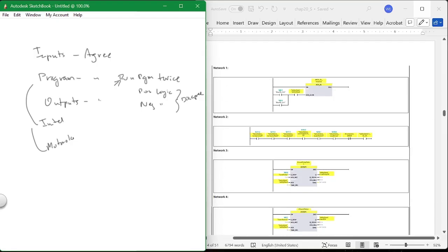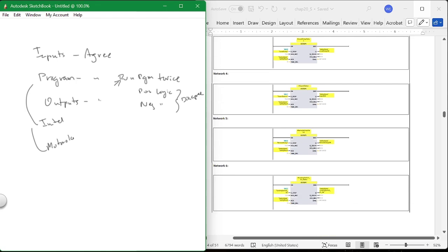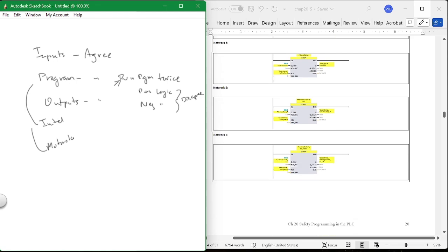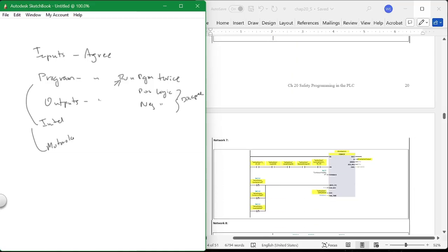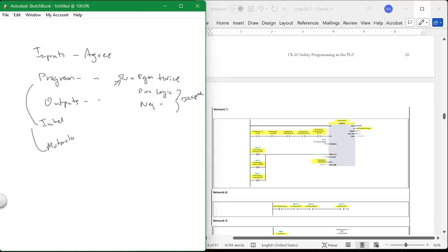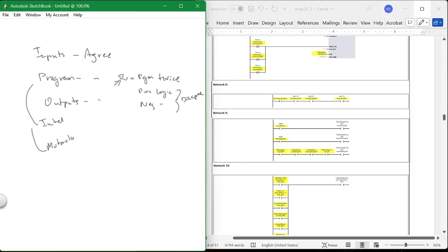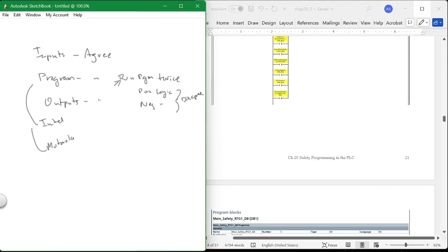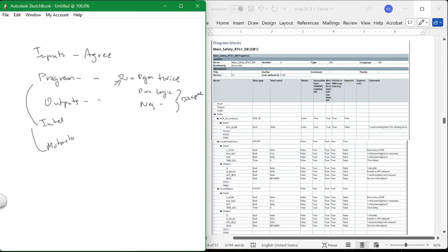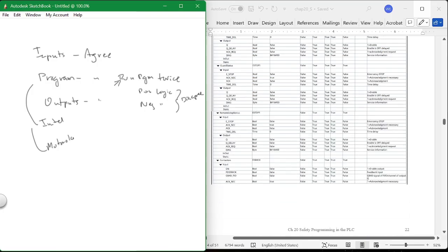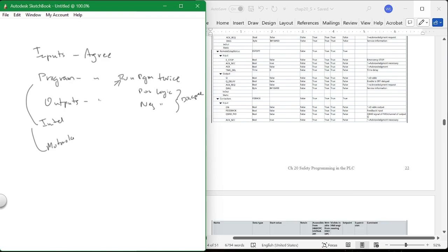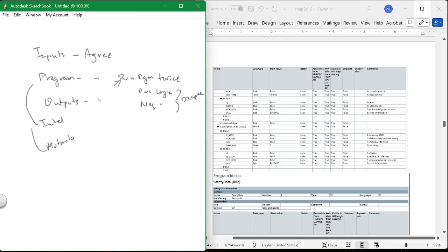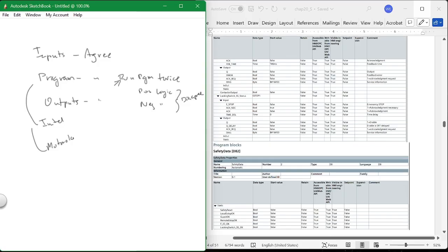But in so doing, you're going to learn an awful lot about how this subject is, what it does and how it works. Okay? I told you this before, but one of the outputs is a category 4 output. The others are category 3. What's the difference is the power supply. There's a power supply in there that actually has a pulse in it. And if you wire it to a regular power supply, it will not work. It only works with its own power supply. If you wire it according to the drawing right here, it will work.